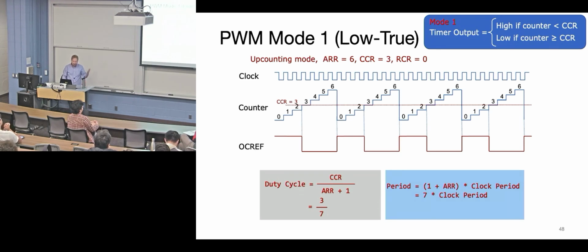Now these are trivial cases. Usually you're counting up to some large 16-bit number. There is a 24-bit counter on your device. I know there is. I don't know if there is a 32-bit or 64-bit. I haven't looked through the data sheet in a long time. But you could also concatenate timers together. We'll talk about building virtual timers where you can keep track of time in software based on a smaller timer or a hardware timer.